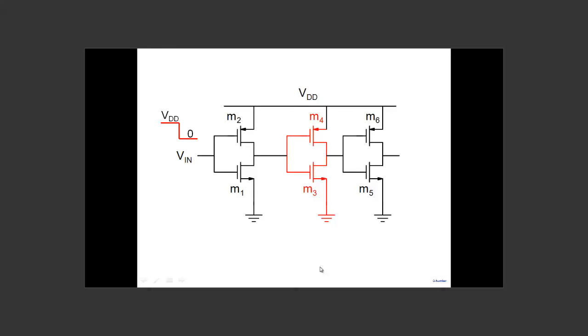All right, so the delay that we have been talking about is for an inverter like this, and we switch the inverter abruptly. But note that this is not a typical inverter. What I just analyzed is not a typical inverter. If I look at a chain of gates or a chain of inverters, this is more typical. Why is it more typical? Well, it has a load. Every inverter or every gate will have a load. So it does have a load and is being driven by another inverter.